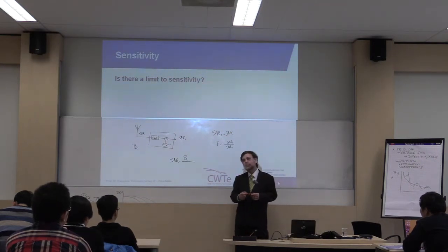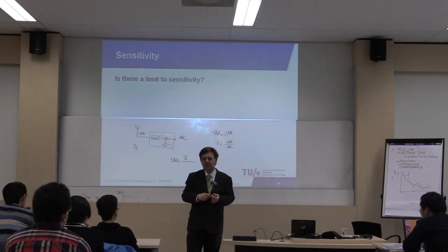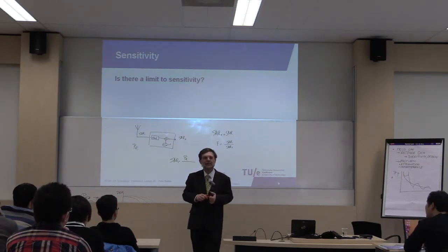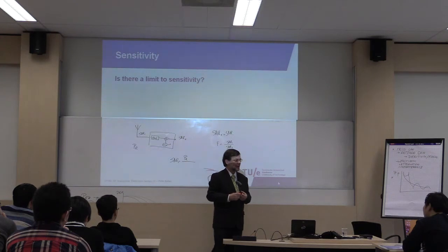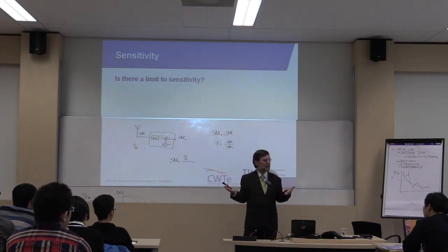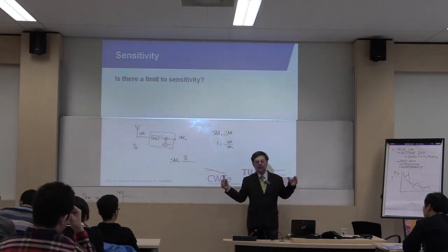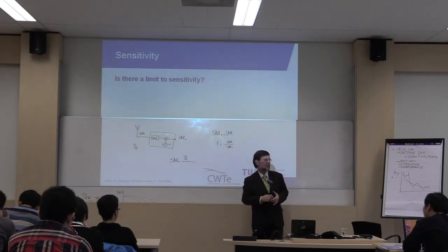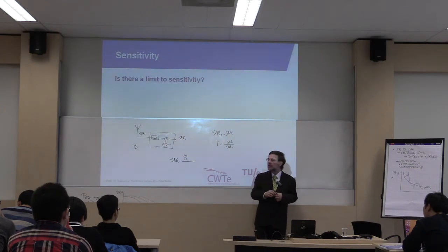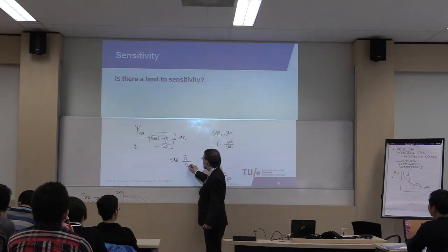And thermal noise comes from the fortunate fact that the temperature here is non-zero. Even though when you walk outside sometimes you can doubt that. But in fact it's still non-zero Kelvin. It's definitely much higher. And this high temperature causes noise, basically because all atoms, all ions are moving, they are shaking, and the electrons get influenced by that, and you get small variations in currents and voltages. And that means that we have a noise power at the input.